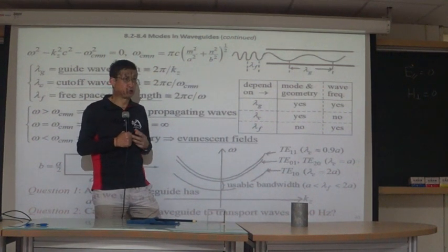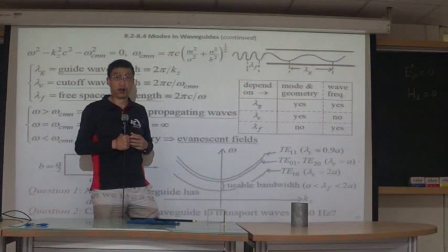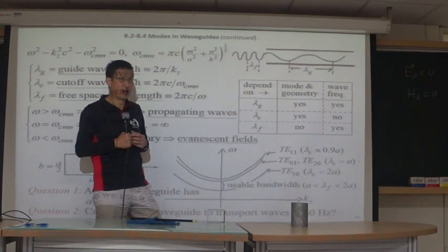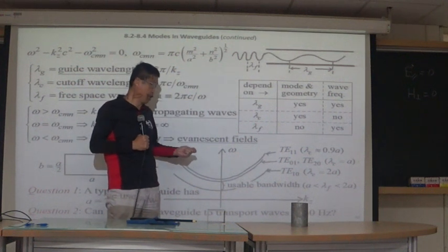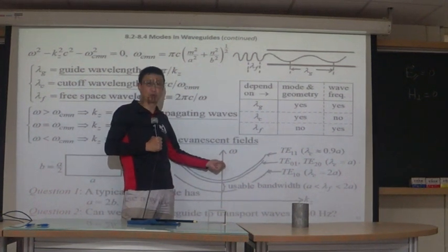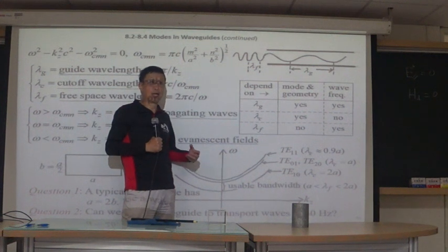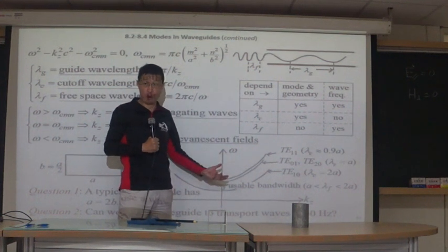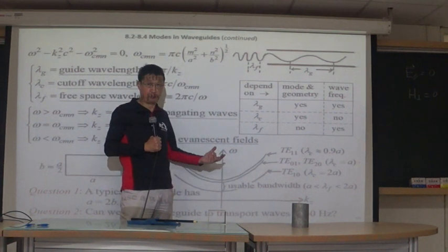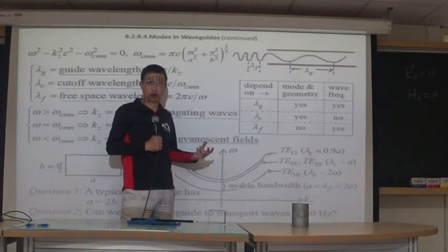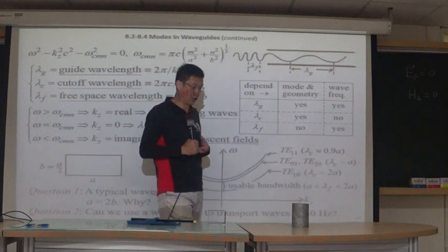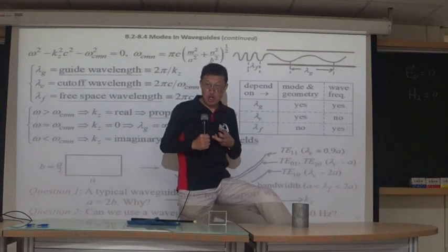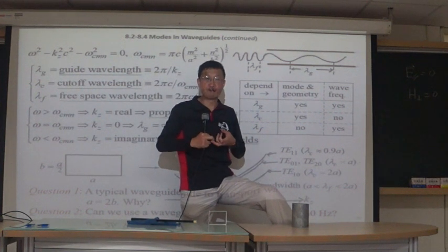How to control these modes? That's a big challenge. If you inject a signal into a waveguide, you can excite all the modes. That's a big problem. That will result in very interesting physics, called mode competition.